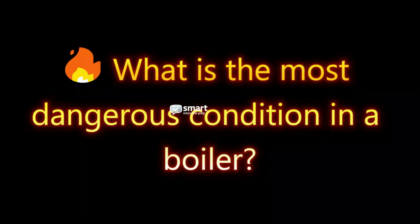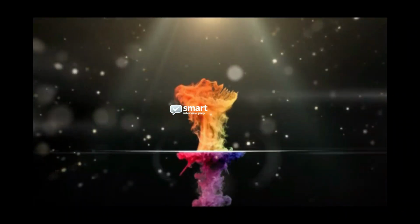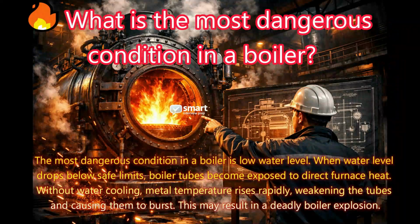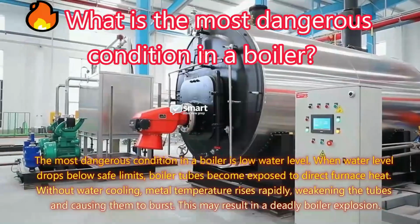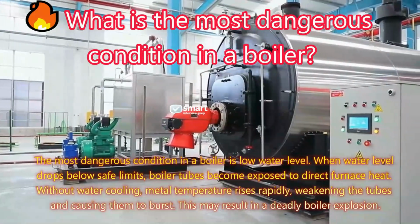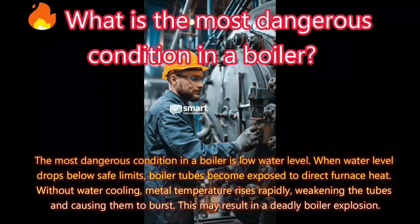What is the most dangerous condition in a boiler? Answer: the most dangerous condition in a boiler is low water level. When water level drops below safe limits, boiler tubes become exposed to direct furnace heat. Without water cooling, metal temperature rises rapidly, weakening the tubes and causing them to burst. This may result in a deadly boiler explosion.